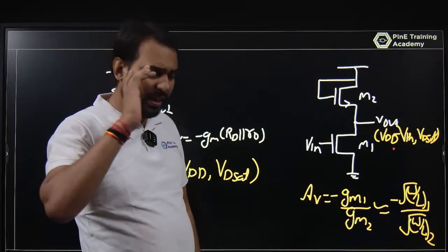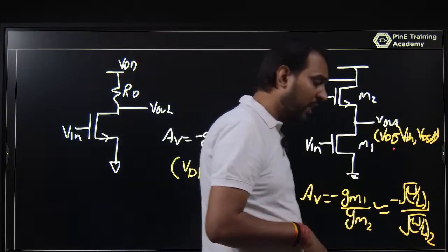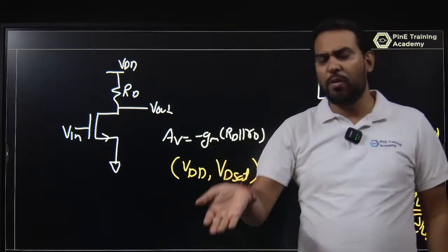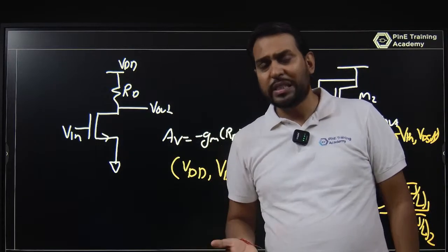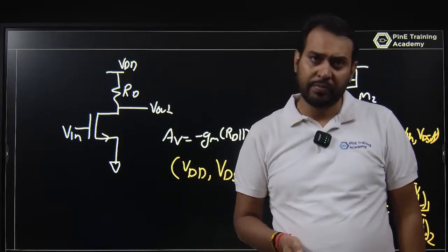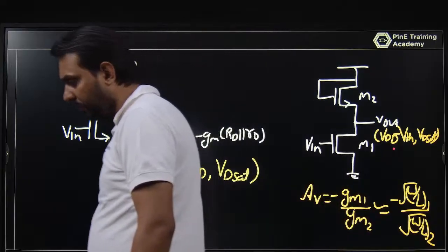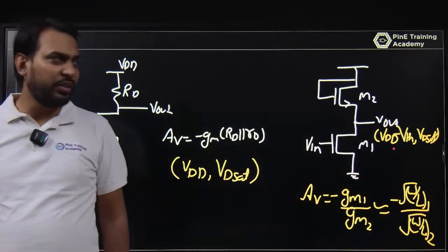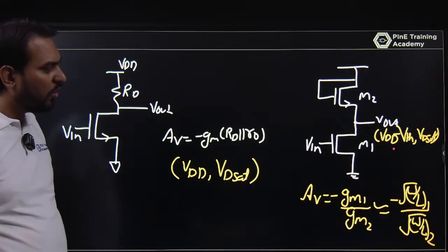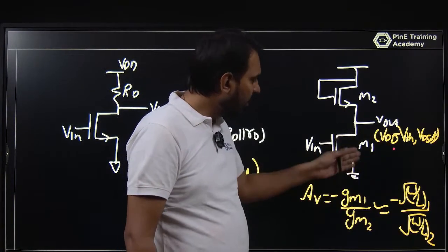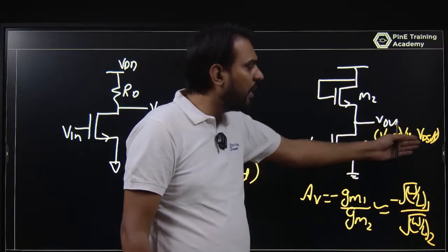And we discussed that in PMOS charging or NMOS charging. So if you are using a pull-up network as an NMOS, the maximum voltage possible at the source side is VDD minus VTH. For a PMOS, the drain will reach VDD. So PMOS is good for charging and NMOS is not good for charging. So it is VDD minus VTH, and that maintains saturation from VDD minus VTH to VDS side.